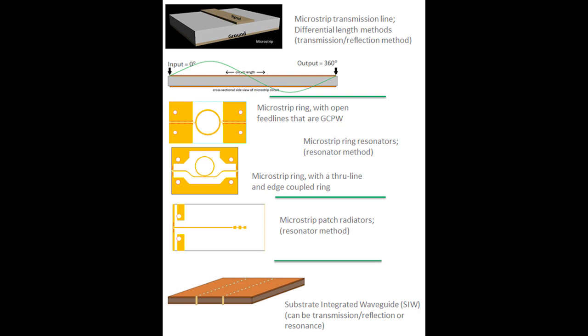Where it resonates, it's pulling energy out at a very specific frequency. So for the insertion loss curve, you get a little dip, or a suck out as they call it, at the point where that ring resonates. You can basically take that, put it into a field solver, and extract the dielectric constant based on where that dip happens in frequency.